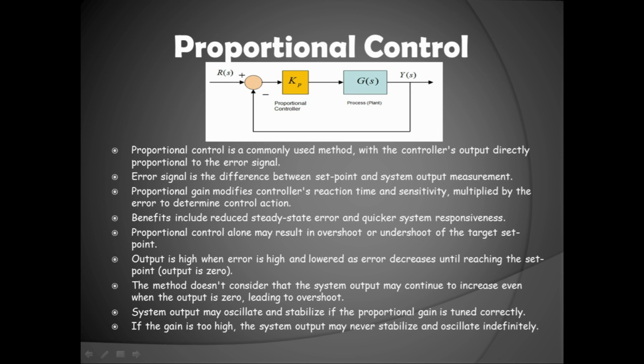However, the heater will remain hot, basically, for a period of time. And this might cause an overshoot. This is why tuning this controller is really important. However, in other control methods, we can solve this issue and we will see how when we explain them.